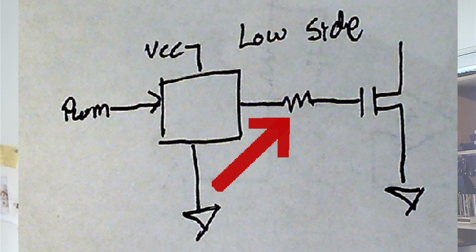And designing these is not trivial, but once you get the hang of it, it's actually not so hard. Really the big thing is to make sure that you have enough current driving capability, that the voltage input is compatible with your switch, and that's the big stuff. You're going to choose a gate drive resistor that's going to control how fast the switch turns on and turns off.